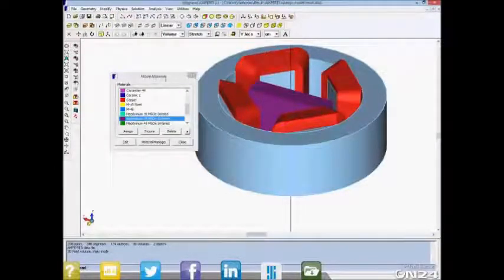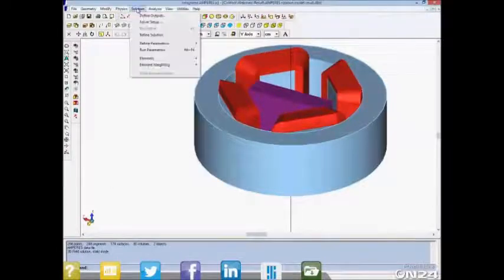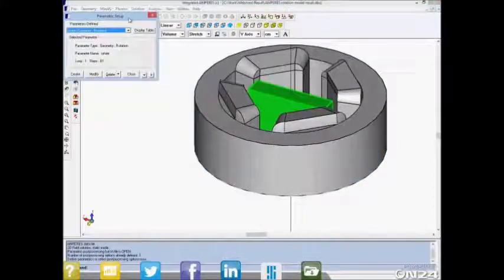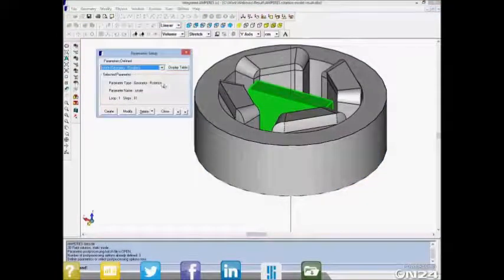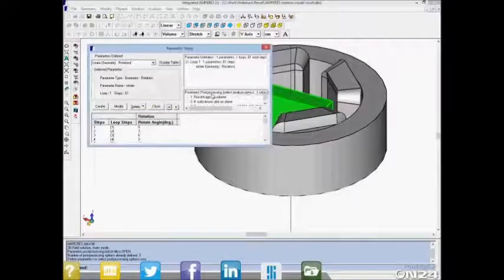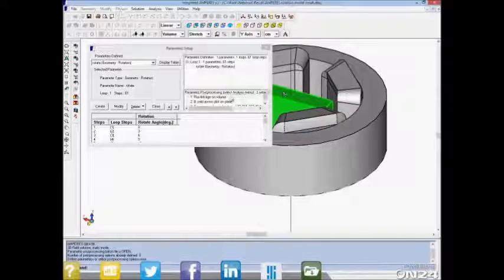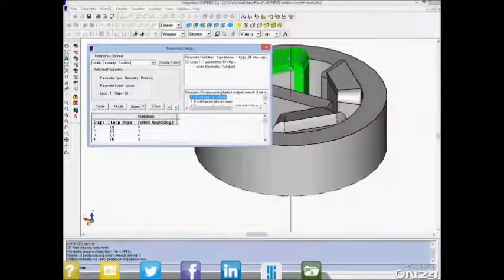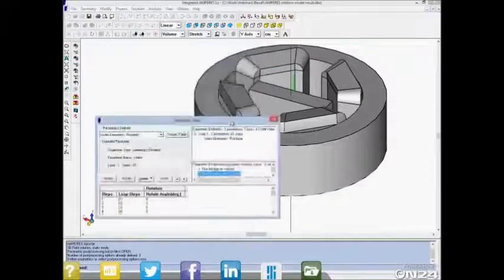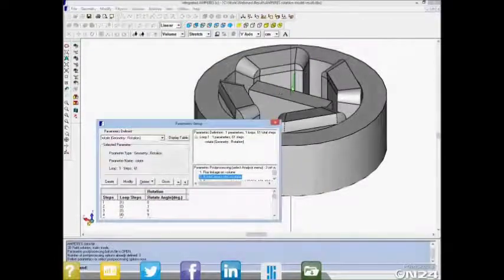The first thing that was done with this model for that purpose was to simply set up and run a parametric. With the parametric, you can vary things like rotation, you can vary current in the coils, and so on. So this particular parametric said, let's rotate the magnet by some amount, and let's compute the flux linkage on one of the coils. Just for feedback, let's produce a B-field plot on a plane that slices through the model. And let's also get the torque on the volume.